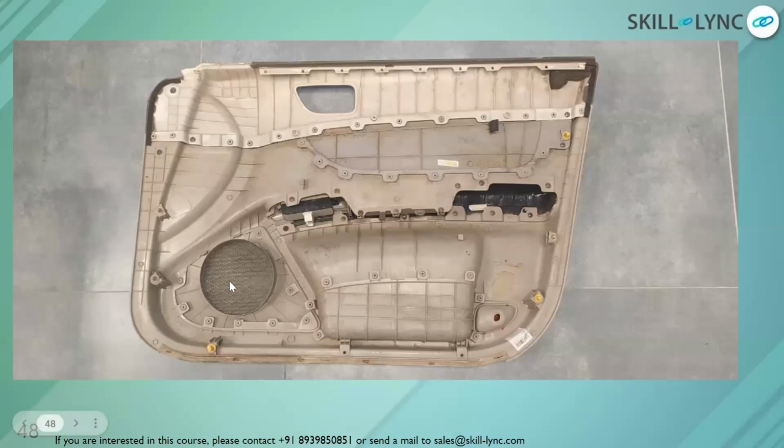And then on the speaker grill again, you can see some honeycomb rib structures. On the other areas which are longer components, again you can see rib structures available. Okay, on the other sides, on the top of the component also, you can see some push pins as well as other components actually available for joining operations to be performed. Okay, so this is how the B side of a plastic assembled part will look like finally for a door panel.